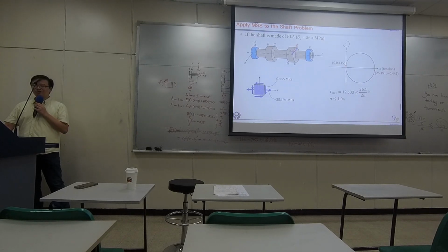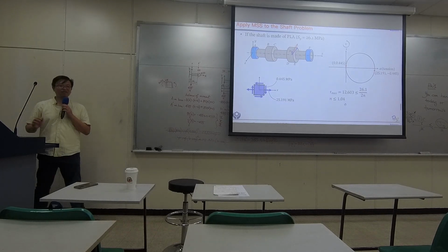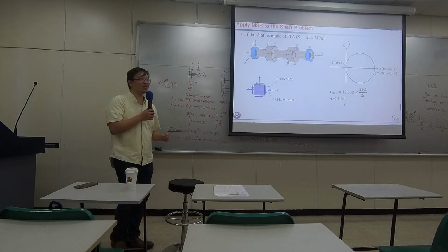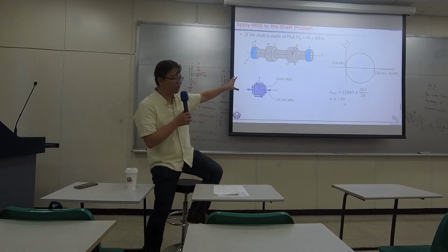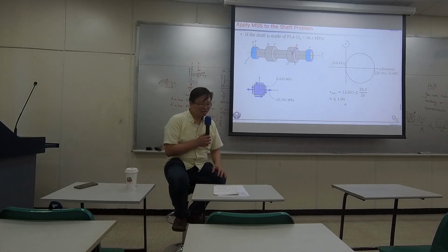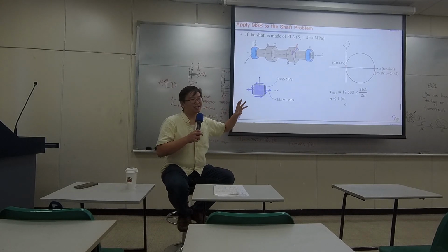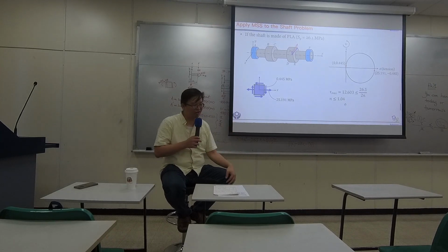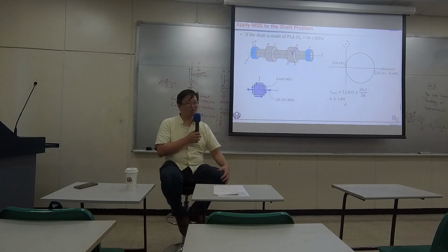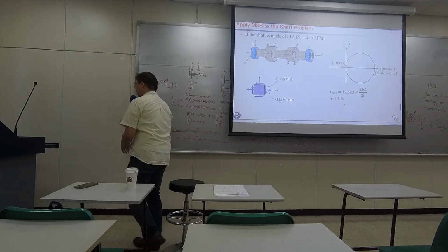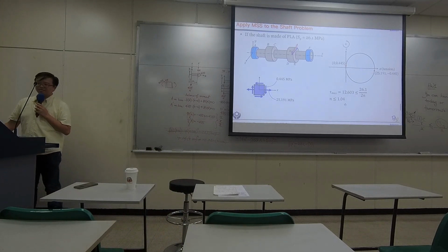Then you greatly reduce your design limit, and now you only have a safety level of 1.04. So if this whole thing is made by a 3D printer, then by carrying the same load, it's about to yield. It's about to break, because your safety level downgrades to 1.04. Okay?